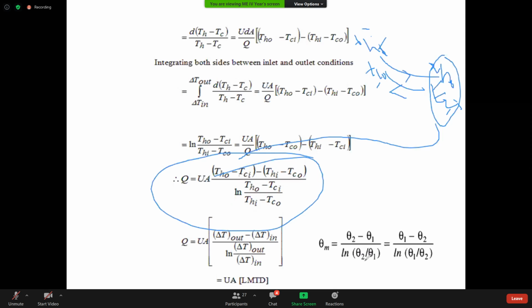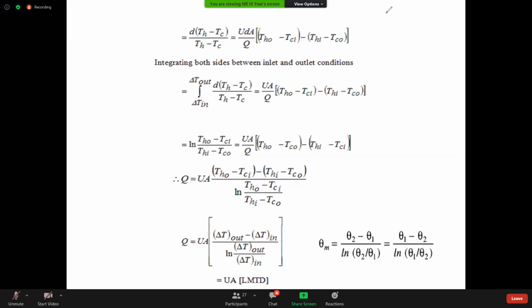Like that you have to write. The only thing is for LMTD you have to derive it. Definitely there is a compulsory question on counter flow. So UA is there, this is the LMTD. We prove it is the same LMTD because we know Q is equal to m cp delta T for the hot fluid and the cold fluid, and based on that we substitute these. So this is the way you have to do the derivation, and the problem will also be based on this one way.